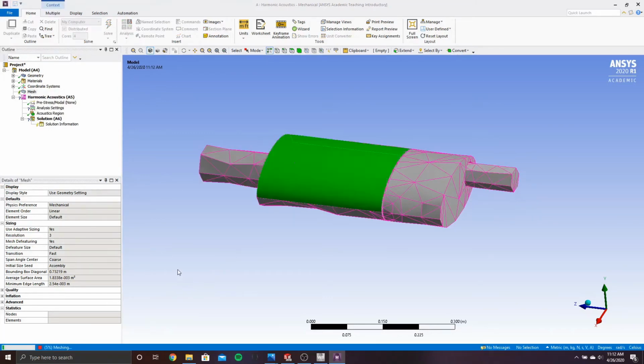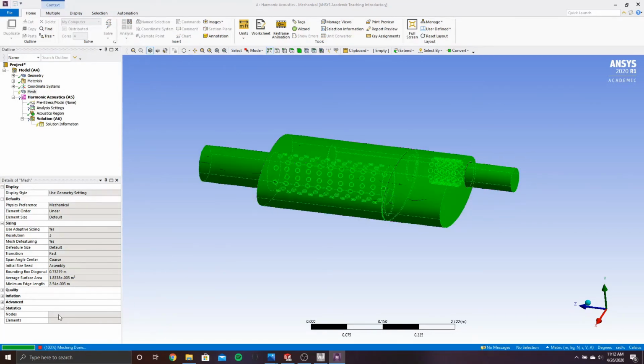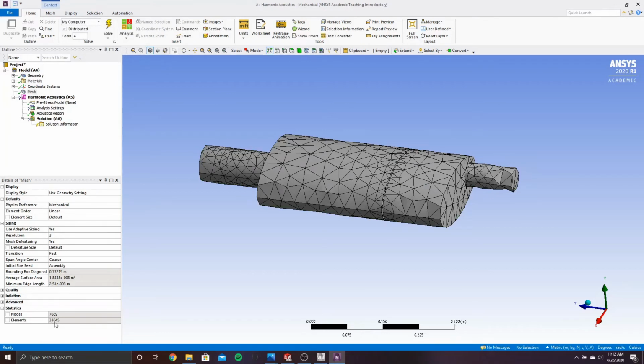We're trying to get the closest number we can to get the best mesh. So we just surpassed 32,000. If we set up the analysis and ran it, we'd get an error saying there's a limitation in the product license we have. So we're going to have to bump the resolution down slightly.